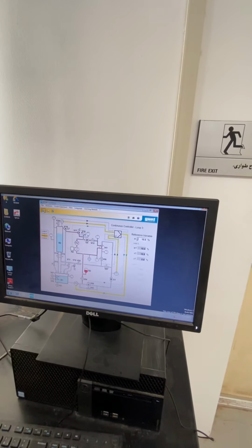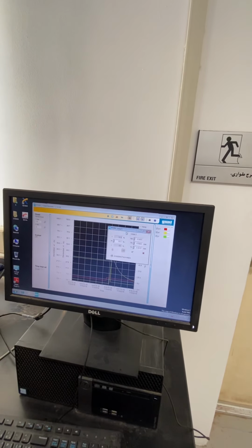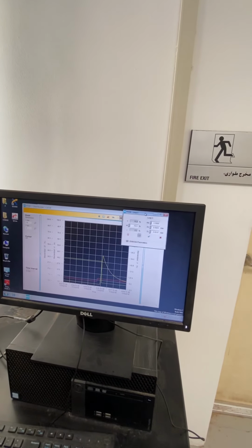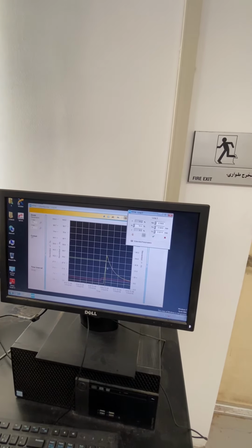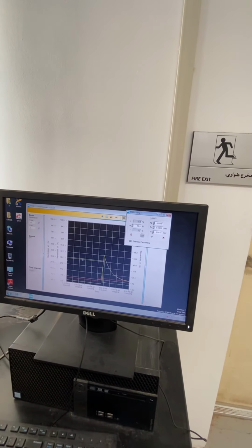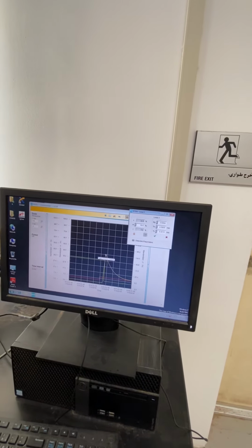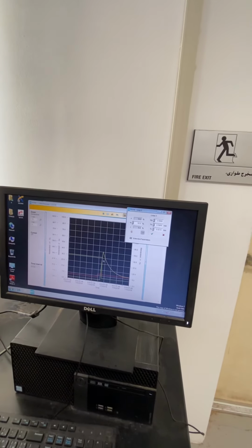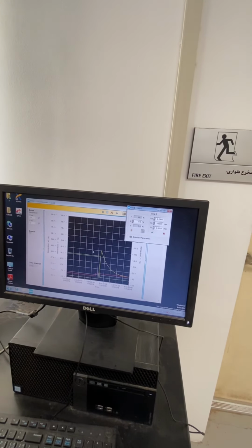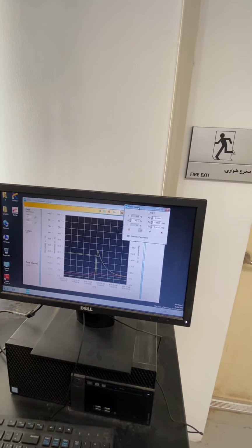Okay guys, so let's have a look at the process trend. That was for the manual control. And the spike right here is when I made a mistake. I didn't change the output signal. It was for the flow rate control, and you can see that the process value went up so quickly. The level went up so high in just a few seconds, and that's why I had to manually reduce the output signal from like 44%, I guess, to 5%. So the level started to go down.